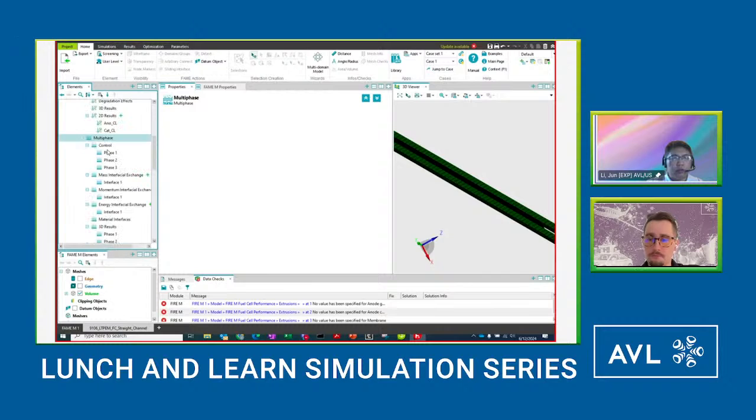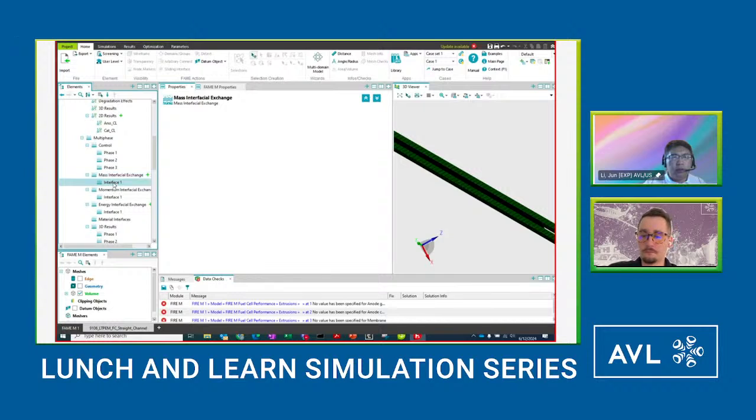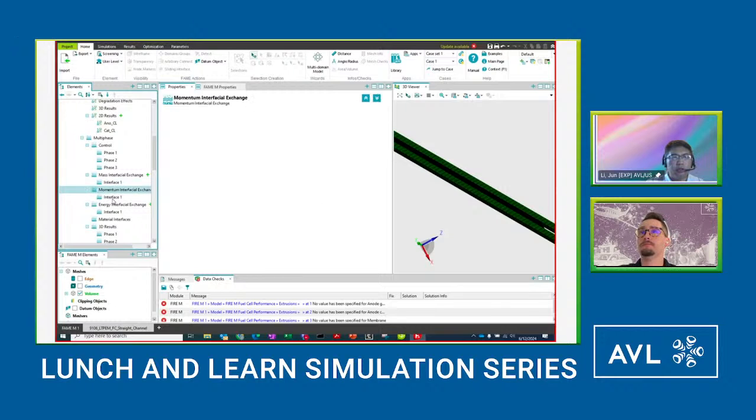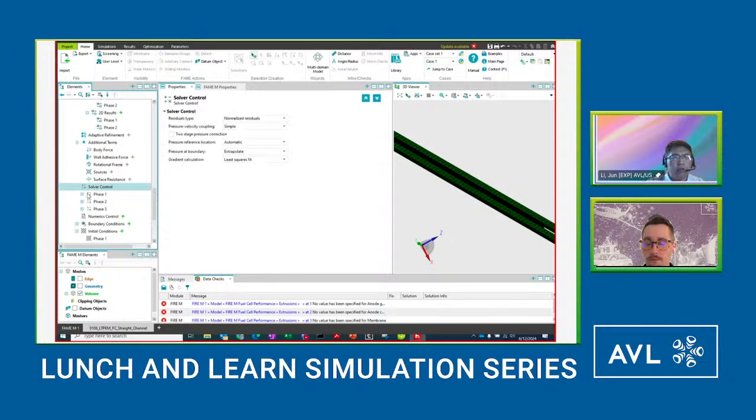And again, we're solving the multi-phase flow in this PEM fuel cell. So these are the multi-phase flow settings, specifying the mass interface exchange, momentum interface exchange, and so on. The last thing would be the species transport for the gaseous flow. And then we have the solver control.